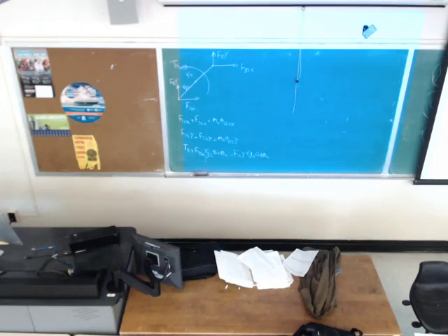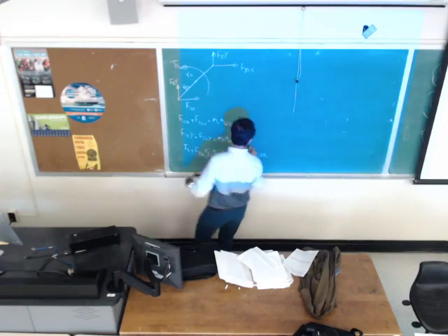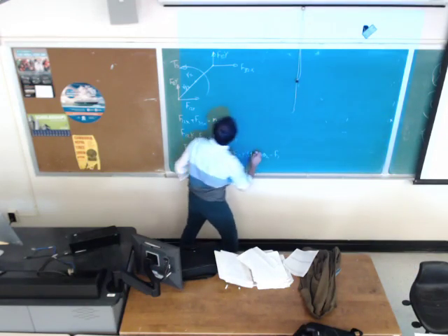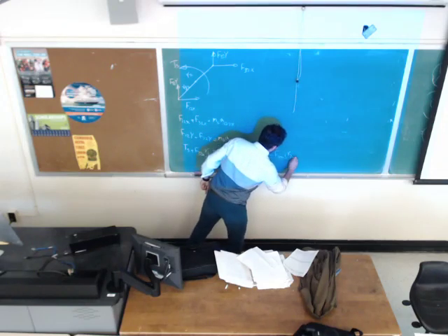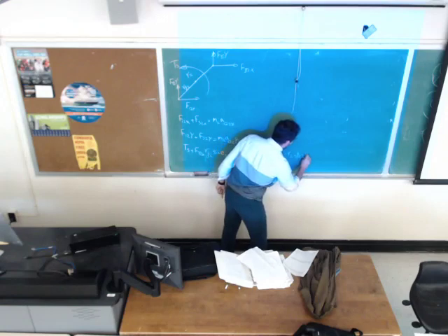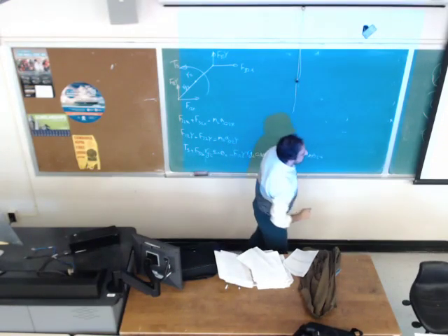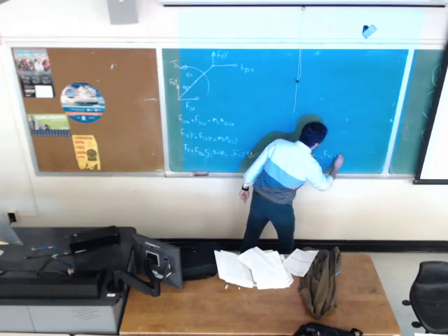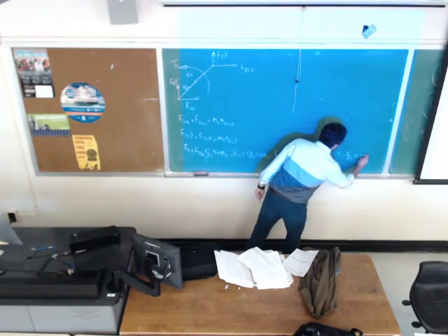R2 minus Rg2 will be this length. This force times this distance, which is R2 minus Rg2 times sine of theta 2, is making torque clockwise, negative, due to that force times the length. This is the R2 minus RG2 times sine of theta, so it's going to be perpendicular. So minus, and plus the last one, F3 to R2 minus RG2 cosine.